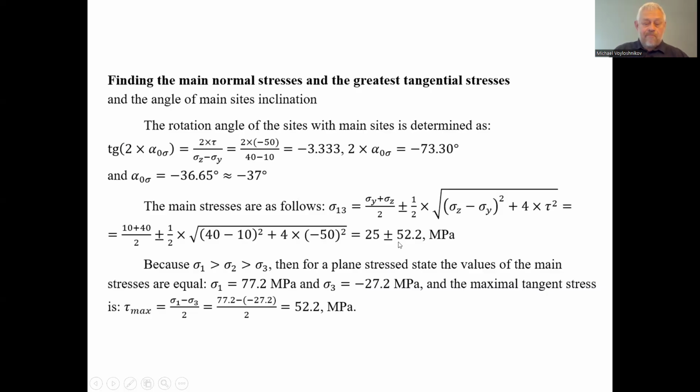And now we see that the second normal stress is number 3, because number 2 is the stress directed parallel to the abscissa axis x, directed to the right. For this flat stress state, the stress applied in the direction perpendicular to the plane of consideration of the flat state will be equal to 0.